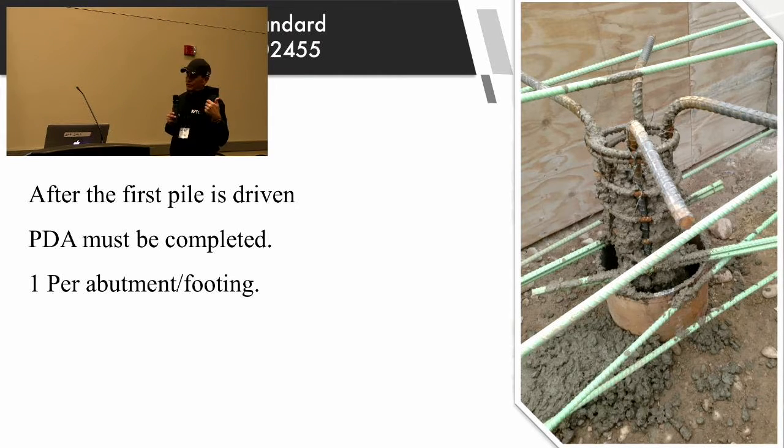A lot of times it'll slide over and butt up against one side of the pile. They're going to have to do whatever they need to make sure that cage is centered, again, to transfer all the loads down through the pile like it's supposed to and get full embedment of that pile.